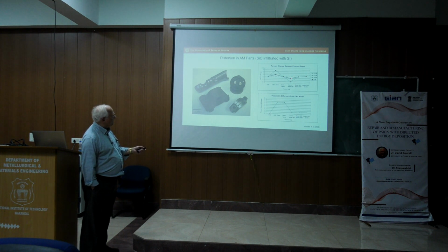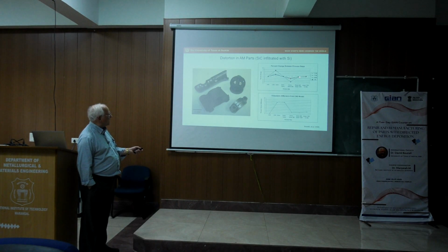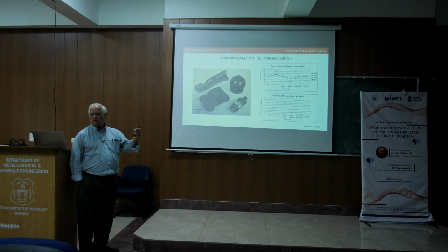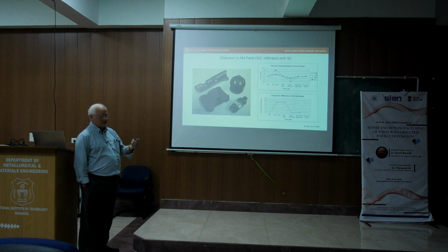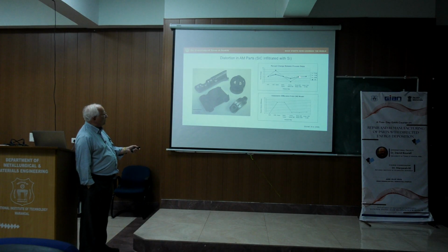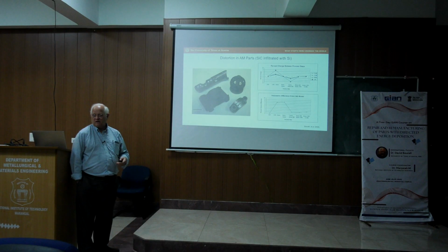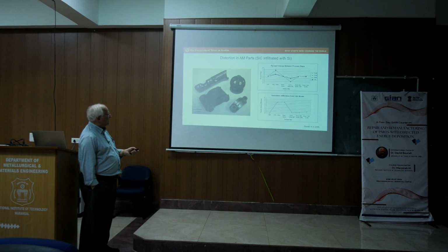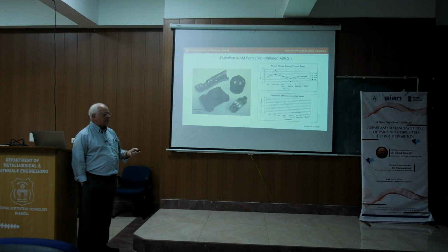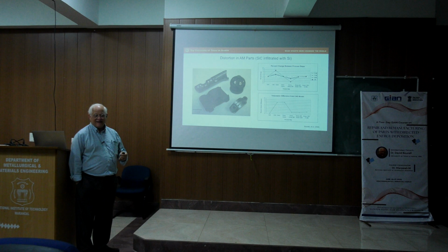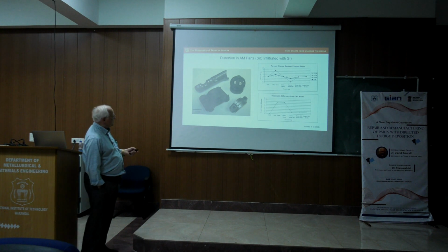And then on heating it up to the high temperature, 1750, a slight expansion. So we heated it up and just pulled it back down to room temperature and did the measurements. And then finally, infiltrating with silicon results in very little dimensional change. And so it's sort of serendipitous that we start off at 0, and we end up at 0 after all this fluctuation in between. So we sort of lucked out in that respect.